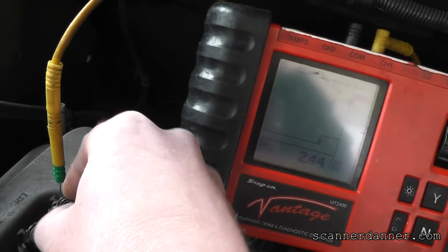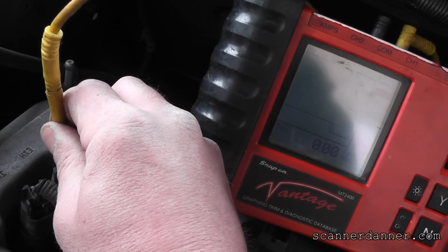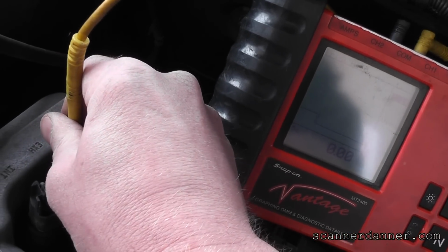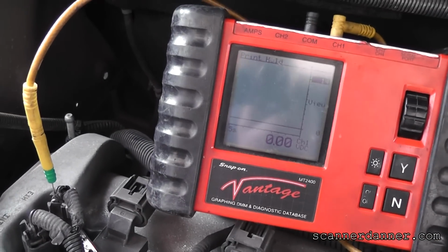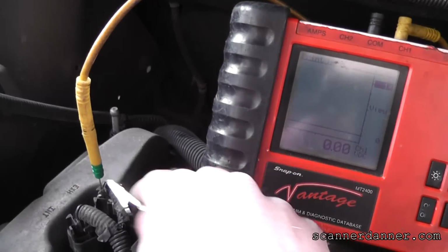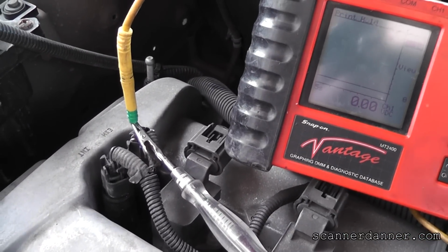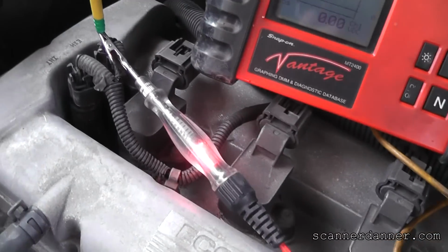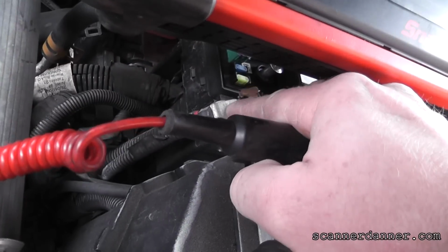For the naysayers, I'll redo it. Ground to ground, loaded circuit. It's what we want to do. And there's multiple ways we could do this. I could actually just take my test light, switch it to battery positive. In fact, I'll do that on this one. Oh wait, you're going to hurt that computer. No, I'm not. There it is, right there. Test light to battery positive. I'm just touching on the post.